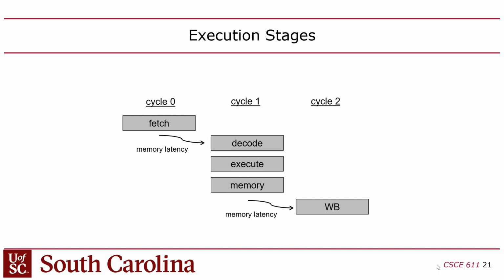That instruction will have data that passes into the next stage. So you're going to have a few pipeline registers to convey data from cycle 1 to cycle 2. Not many, I think there's only 2. You don't have to have a lot of pipeline registers, but this gives us an excuse to learn how to use registers.